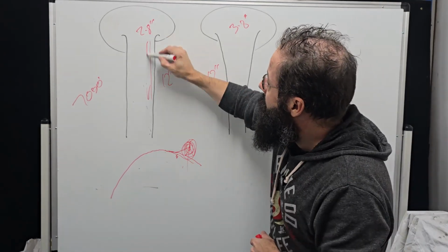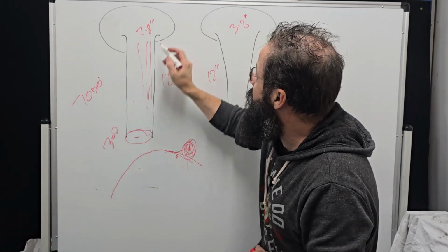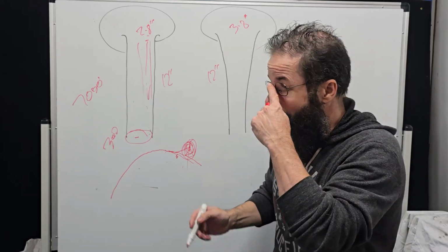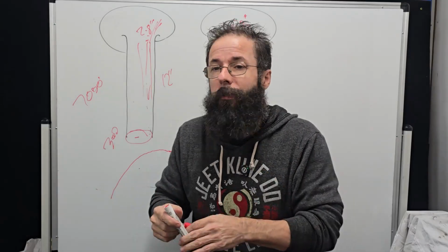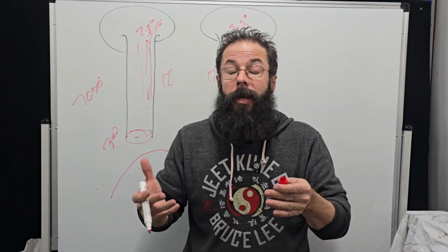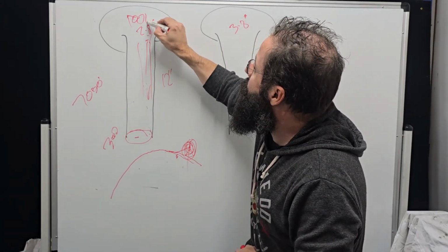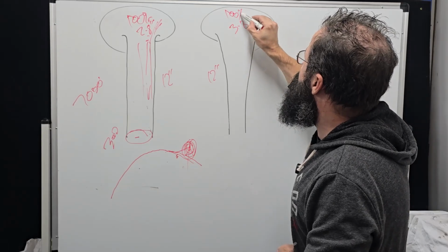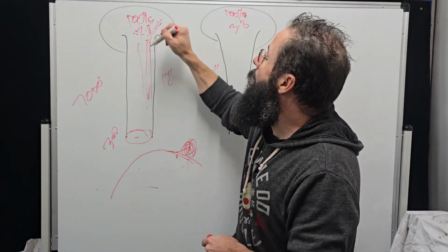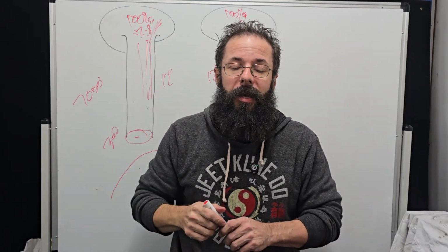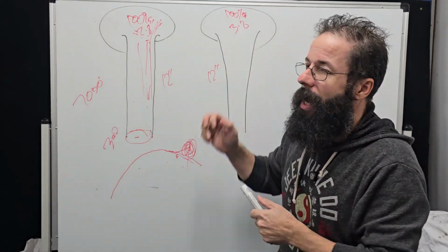And the other factor, so obviously we have too much velocity in a parallel runner, because if this here is at 300 feet per second, so is this. Which also means we're going to get far more wash up into the plenum, which is going to reduce the size of the plenum. So even if you were trying to compare two of the same size plenum, if this was 100% of engine volume and that was 100% of engine volume, well, that dynamically now is no longer 100%, because we have far more wash coming back up into the intake, far more rubbish signal going into the plenum than this one would have, all right?